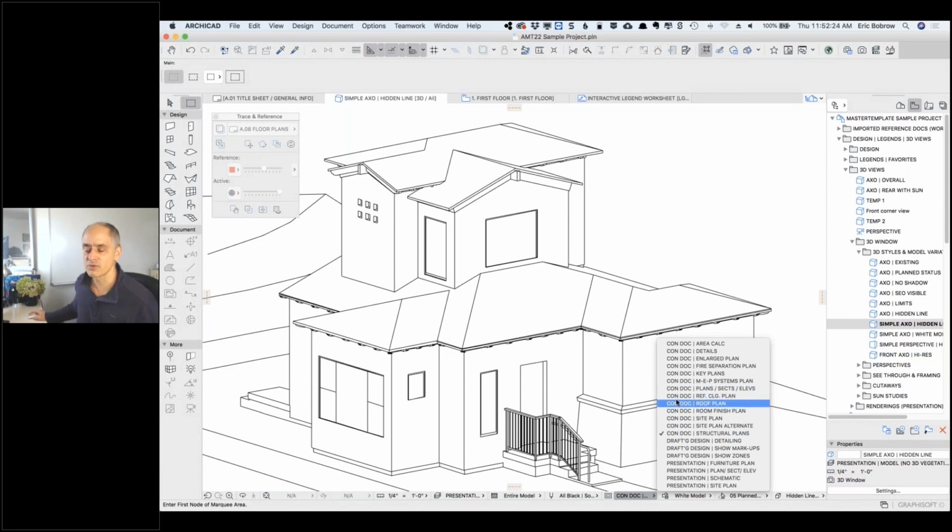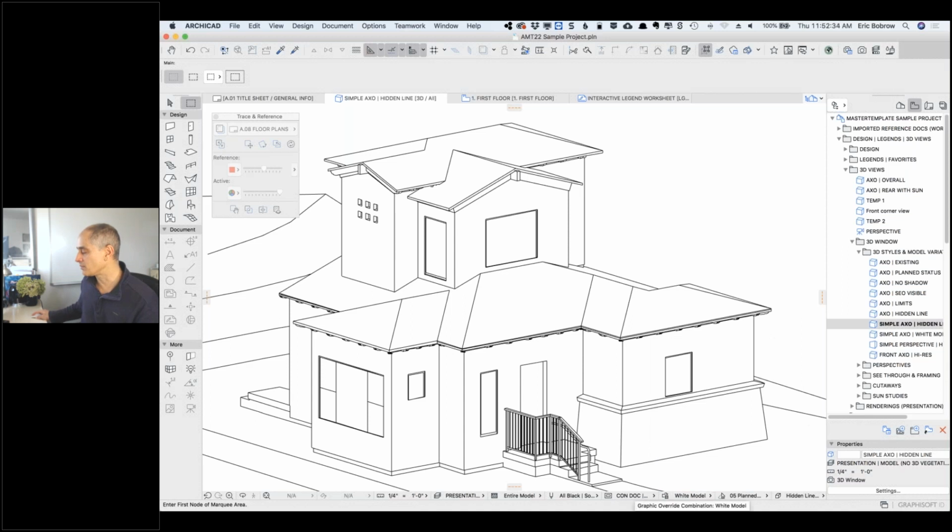And I don't have time to explain all of them, but essentially, there are ones for all sorts of different types of design viewing. And here it's set for a white model. Now, if this was a very complex project, this would help in terms of just working with it, meeting with a client and showing them the basics where they're not focused on detail. And why do you have a windowsill this wide? You know, things like that. You just say, hey, here's where we're thinking of the shape and form. But in a really complex project, you may want it even simpler.